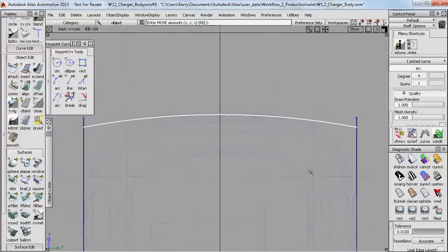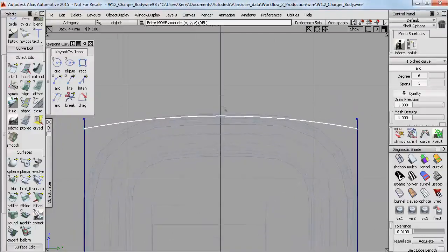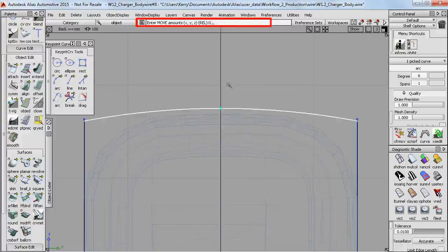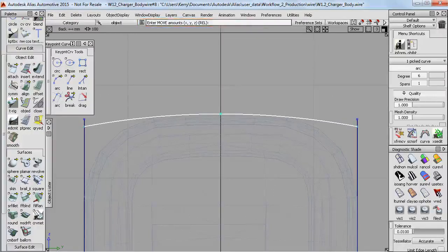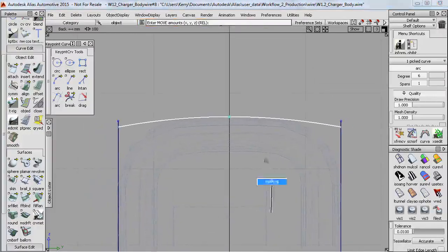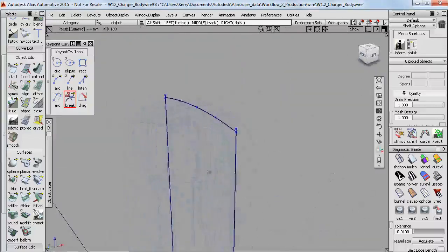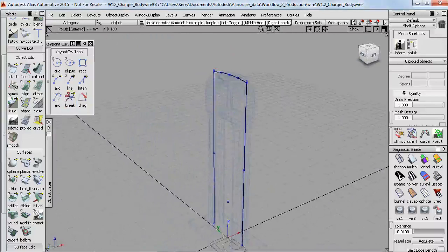So finally I want to get a height that's nice and measurable too. So I'll put the pivot point on the centre and then move it up to the grid. And now I can move it down using dimensions in the prompt line. So I'll just try -25, maybe another 5, maybe just one more. And that looks okay. Now I only want half of this outline, so I'll use the Break at Key Points tool to split that at the key point. And then I'll just go back to the perspective view and make sure that I get rid of the side that I don't need.